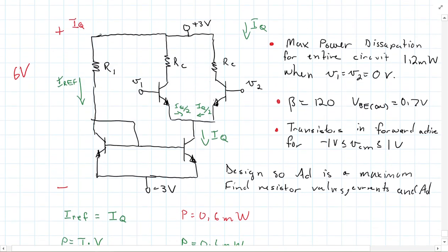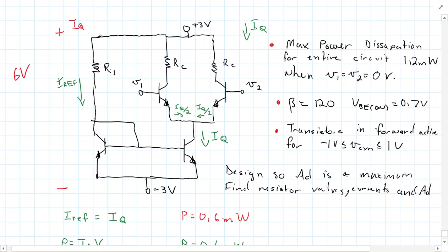So let's go back to the circuit here. I know now my design here, this is a 53 kilo ohm resistor, and that's going to get me a 0.1 milliamp current. And if you want to just go ahead and double check, of course, you can do 6 minus 0.7 divided by 53,000, and we get 0.1 milliamps. Alright, so we get that one.